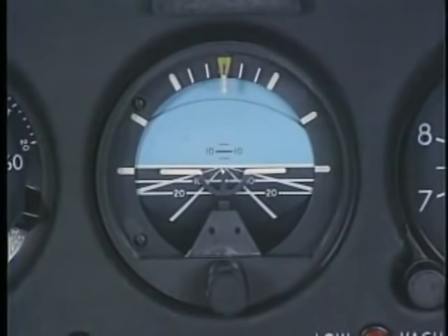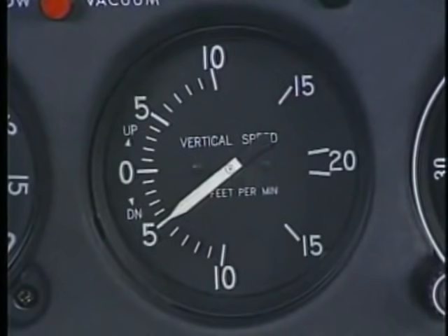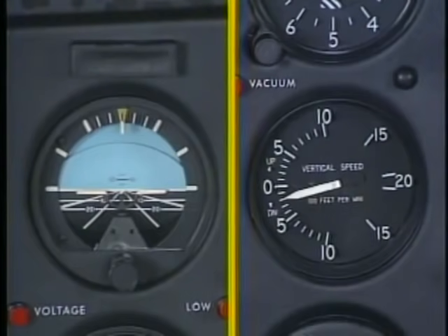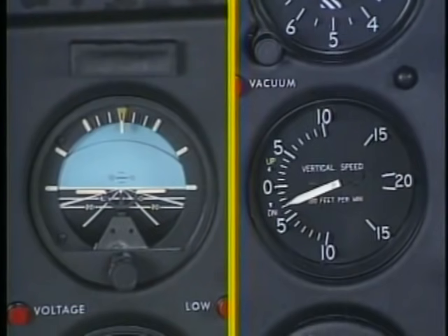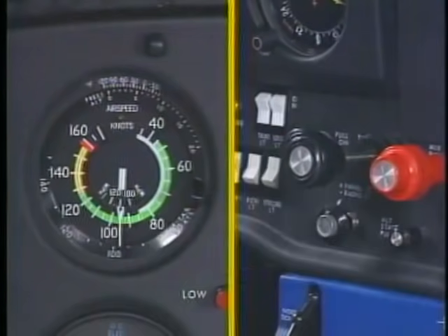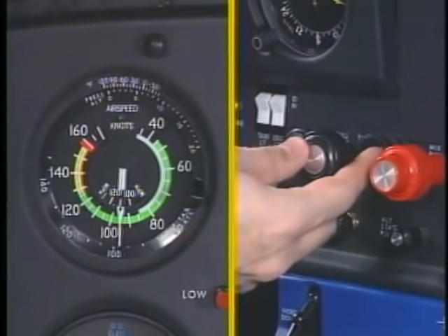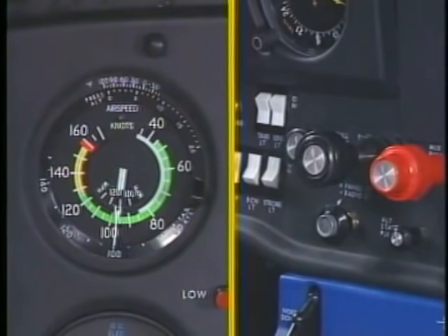Constant rate maneuvers are performed in a slightly different manner. In this case, the object of the maneuver is to establish a climb or descent at a constant rate. After establishing the approximate pitch and power settings using the attitude indicator and the throttle, verify the correct rate by referring to the vertical speed indicator. If a change occurs, you need to make an adjustment in the pitch attitude. With a constant rate maneuver, adjust the power to achieve the desired airspeed.